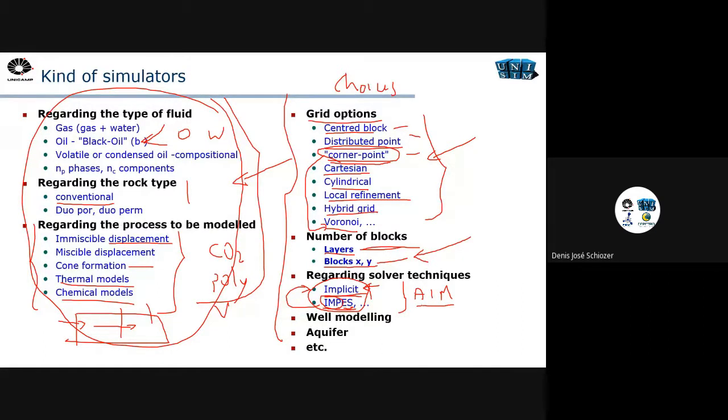commercial simulators developed, it's a special design where, for the blocks where the conditions allow, it uses explicit equations, and for the blocks where the conditions don't allow, then it uses implicit equations. So before it solves the equations, it goes into the conditions of the reservoir, and the simulator automatically selects which blocks we are going to solve implicitly and which blocks we are going to solve explicitly.